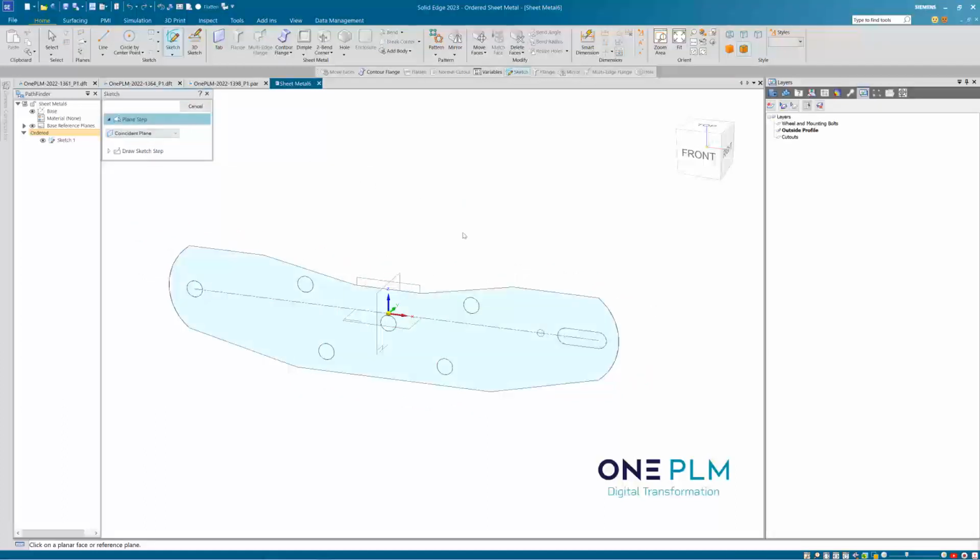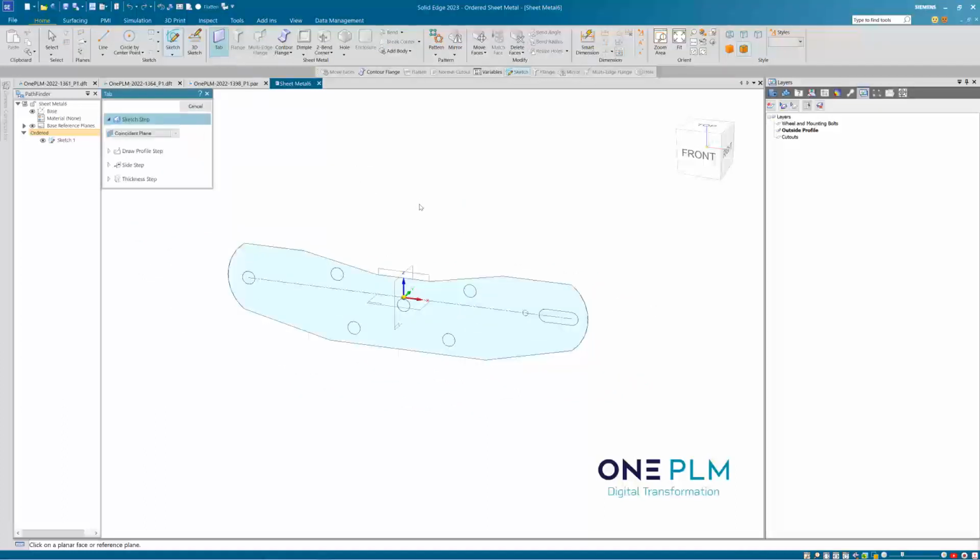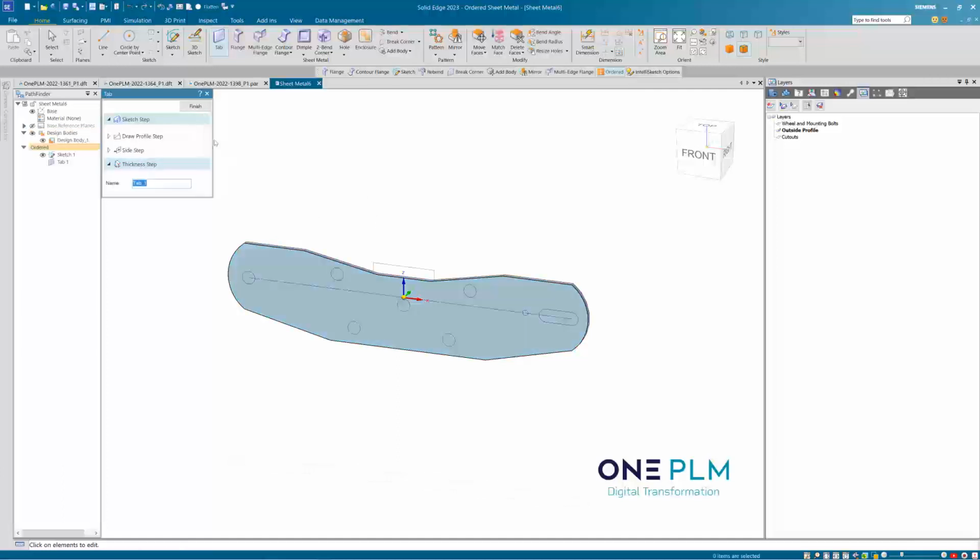and finish, we can then choose our tab command. And on here, if we choose from the drop down here, we can do select from sketch. One thing that I also quite like, if you click the tab command, it doesn't come up with select from sketch. You press the up arrow on the keyboard before you do anything else, that will go to the select from sketch option on there as well. If we choose the chain on there and then accept, that will tab that chain. This probably wants to be about 10 mil thick. So if we go 10 mil thick on there and then finish and cancel.